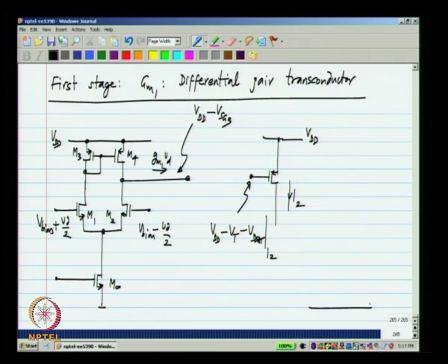Instead, if you had an NMOS transistor, biased at let us say the same current I2, the voltage would have to be Vt, the threshold voltage, plus Vd sat at a current of I2. Now, you see that the output voltage of the first stage is a lot more suitable for biasing a PMOS transistor than an NMOS transistor. Okay. If VDD minus VSG3 has to be equal to Vt plus Vd sat, there is some constraint between VDD, VSG3, Vt and so on. Okay.